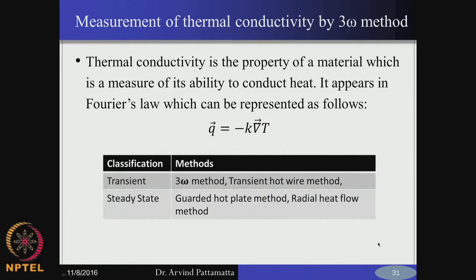Okay. So, all these are with respect to the microchannels, where you look at the fluid pressure measurements, temperature measurements, flow rate, velocity measurements, and so on. Now, if you go to the nanoscale, we are interested in the thermophysical properties, such as the thermal conductivity and heat capacity. These are required for you to, for example, solve the Boltzmann transport equation, and therefore find out what the size effect on thermal conductivity is.